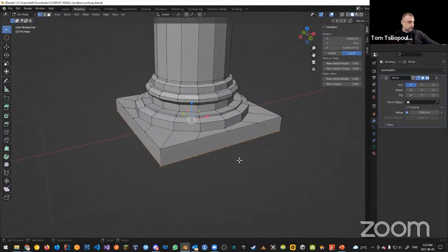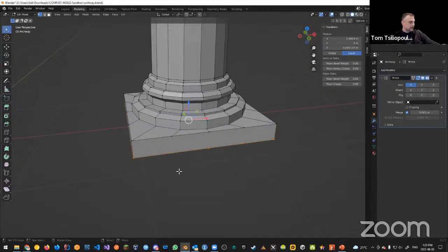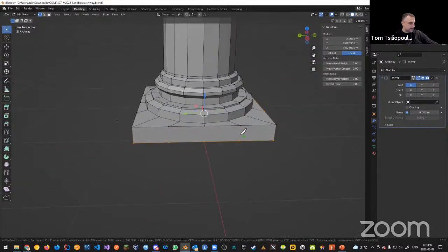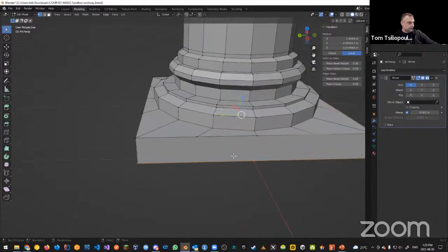A quick way of doing this would be to make cuts, as opposed to getting rid of the face and then doing that edge trick again. We want to make cuts. So again, I can use the K key to make a knife cut between this edge and this edge, and then press enter, and then keep doing that all the way around. I'm just going to use a knife cut between those 2 verts and just go all the way around until we have the proper scenario here.